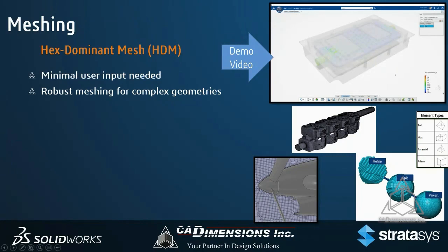So in this case, if we take a look at this propeller blade design, it builds the mesh around the surface first, and then it will fill the volume afterwards, versus the desktop mesher is a Cartesian mesher where it builds the mesh in XYZ space and then tries to fill with really, really tiny mesh elements around the boundary layers or around the inlets and outlets, wherever we specify for the local mesh controls.